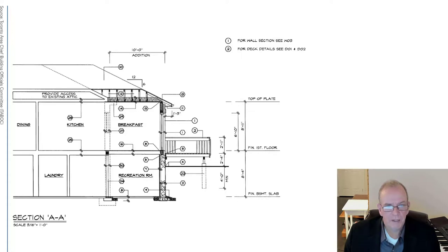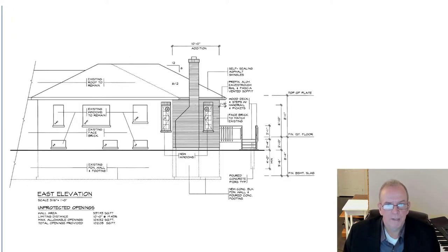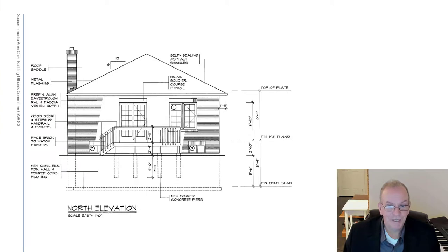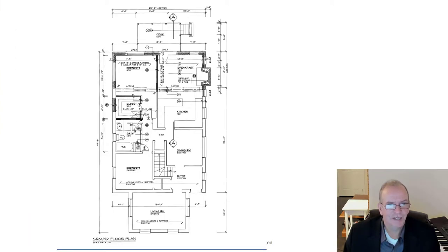Just got to look at it and say, I'm going to figure this out step by step, what the process was and what the designer was thinking, and accept too that not all drawings are created equally. There are good ones and not so good ones out there. The more questions you can ask, that just means more RFIs and more clarifications if you're on your A game, so you don't miss stuff.